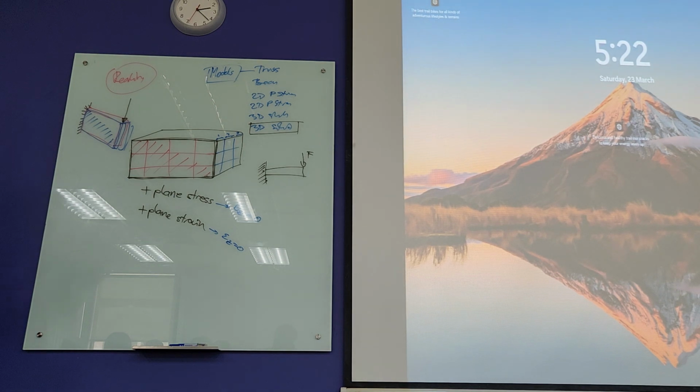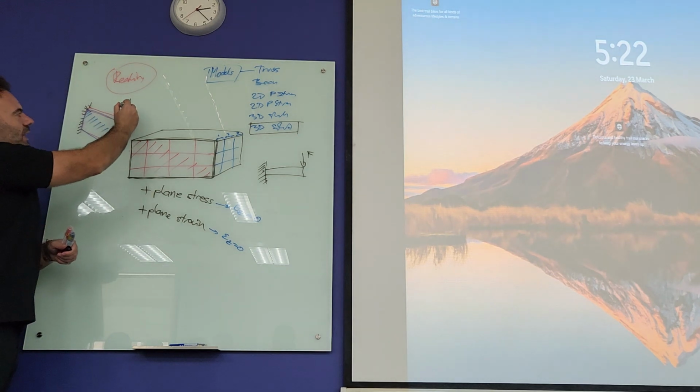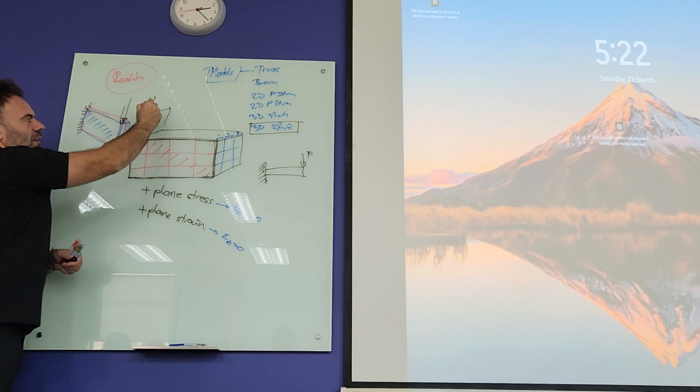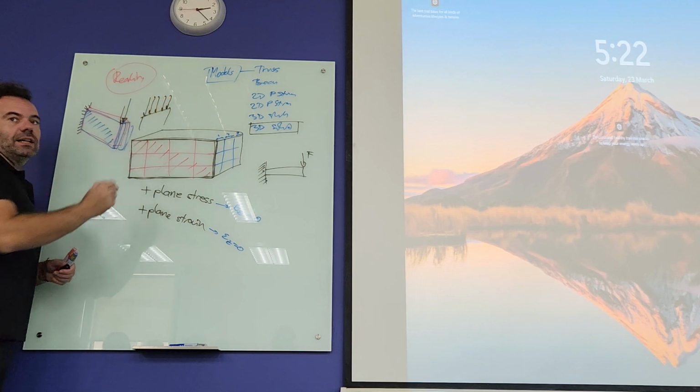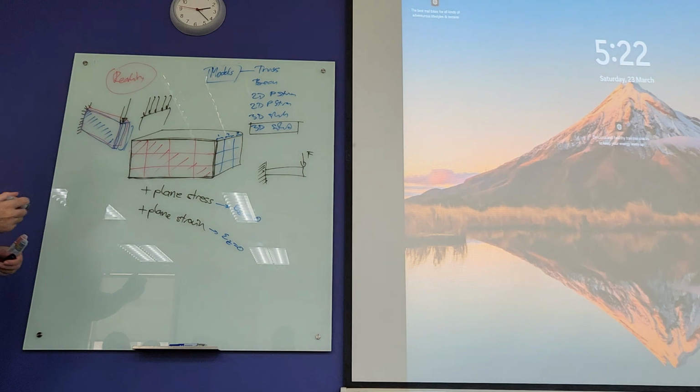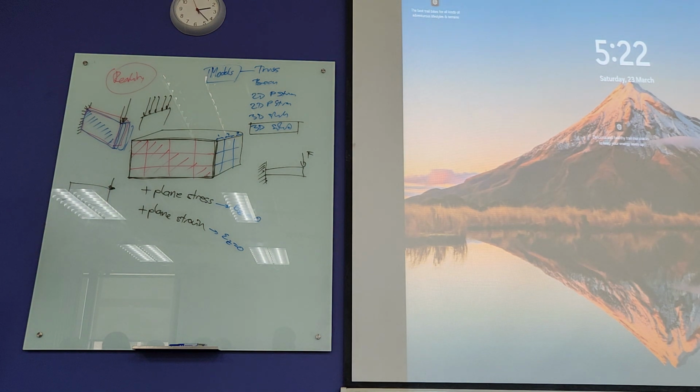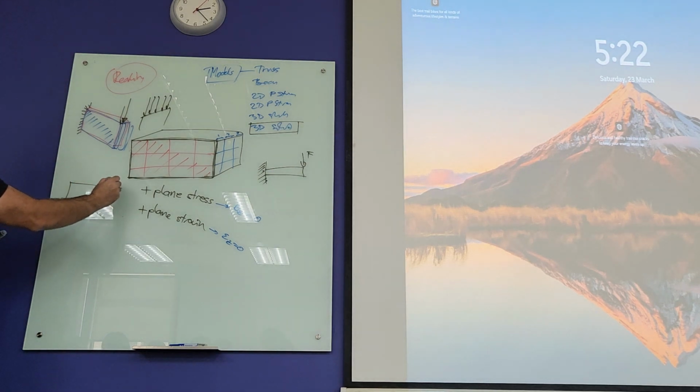What it means is that that load there is essentially applied across the thickness like that. So when you do your plane stress or plane strain model, and you've got a force applied like that, it means that what you're modeling there is a front face that repeats till the end of your thickness. So that force is essentially repeating like that. So it sits on that edge.